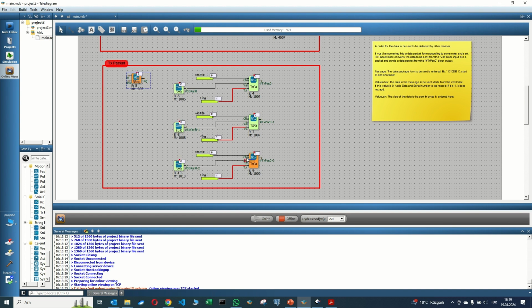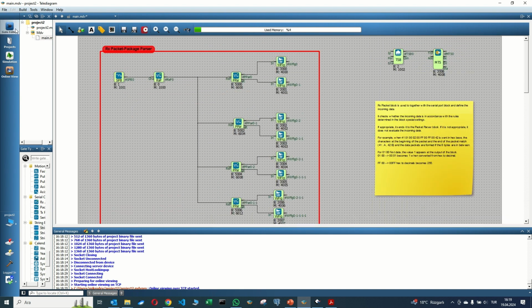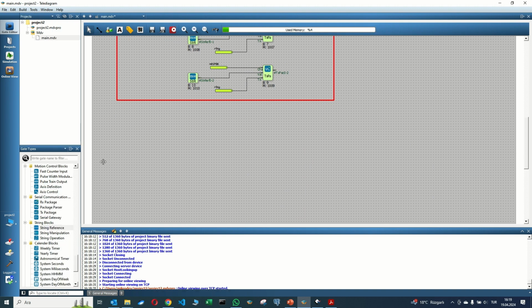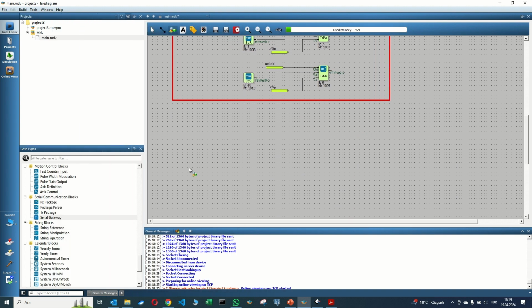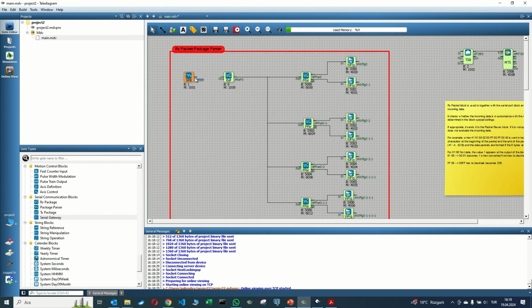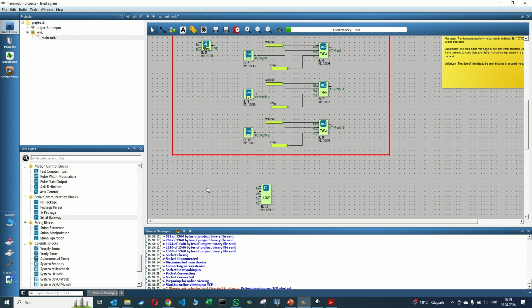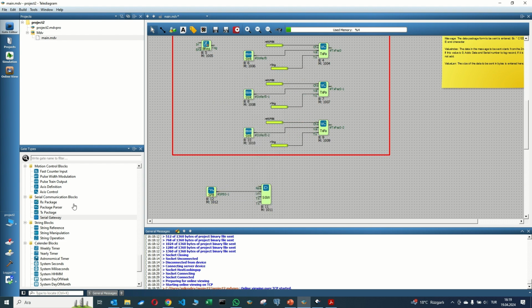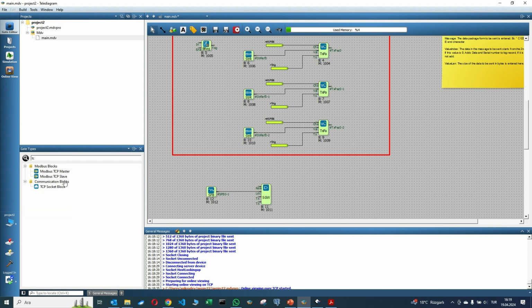Now let's move on to our other block, the serial gateway block. The serial gateway block is used in transparent communication systems. The serial gateway block allows the packets of a device connected via RS-485 or RS-232 to be directly transported to remote systems via Ethernet, GSM, or Wi-Fi without performing any operations. We connected the serial port block to the local input of the serial gateway block. Let's do our tests by opening port 500.